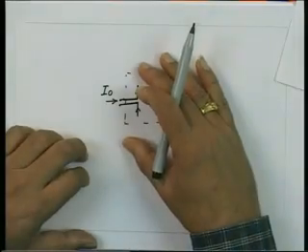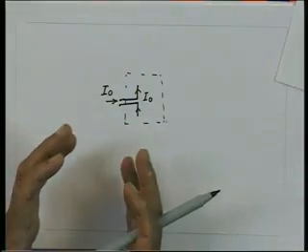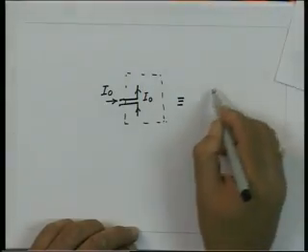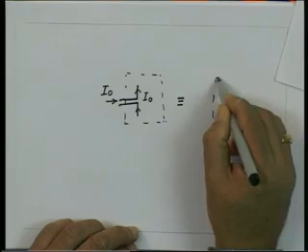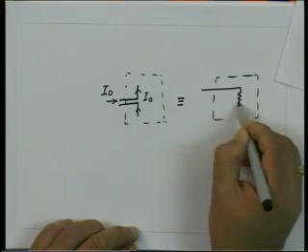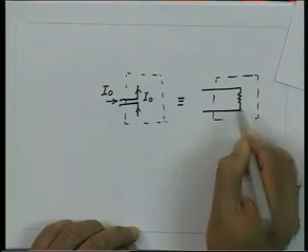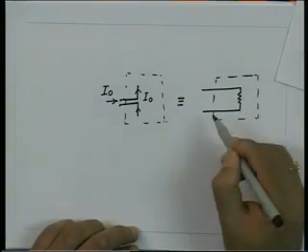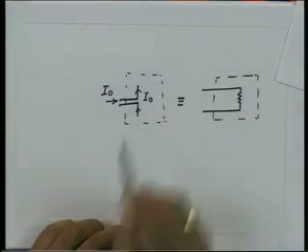So, if I treat this Hertz dipole like a black box, this black box will appear like a resistance. When the current is pumped into it, there is a power loss inside it, and that is the characteristic of a resistance. So I can say this box here, the black box, is equivalent to some resistance which consumes the same power as the power radiated by the Hertz dipole.